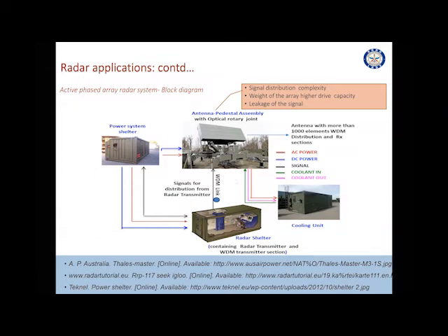So you assume that whatever signals have to be distributed here, if we are able to send it through a single fiber from here, and the distribution happens in the array, that means the transmission of all the signals is happening through a single fiber using a WDM link. And if I am giving it to the antenna, in the antenna I can take the distribution. Here the advantage is instead of having multiple cables, we can use a single cable.